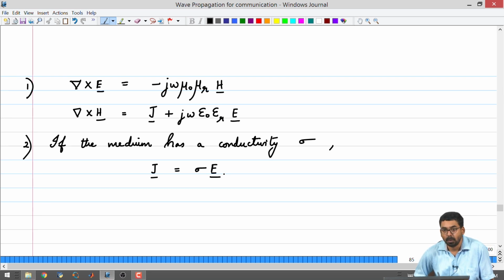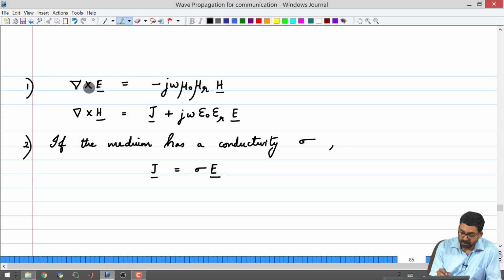The unit of electric field is volt per meter. Correspondingly, on the left hand side I have included a conduction current density. So this means that the first equation does not change, because we did not have any conduction current density related term over there, but in the second equation, del cross H, we can expand J in terms of sigma and E. So we can substitute sigma E instead of J in the del cross H equation.